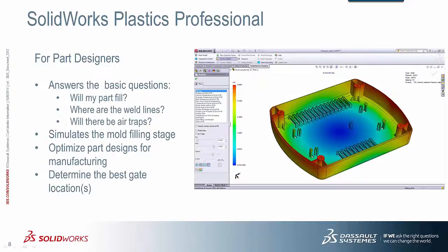The first level is just focusing on the flow phase, answering questions like: am I going to get my cavity to fill? Where are the weld lines going to be? Are there any air traps? This is all on the front end, what's going to be happening, and very relevant to any designer making injection molded plastic parts.